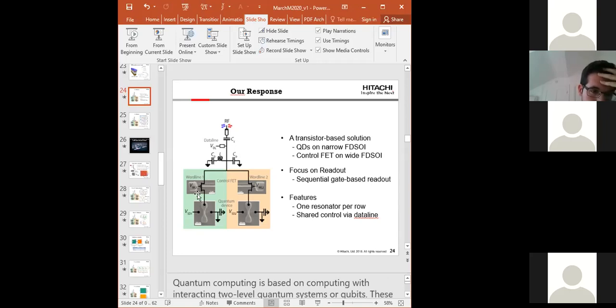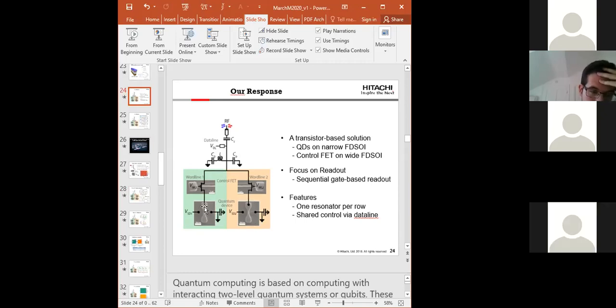And then you disconnect from the data line, and then you go to the next one, and you provide a slightly different data line voltage if you need onto the second device. The caveat there is that the voltage here, while you are not connected to the data line, will vary over time. So you need to manage that voltage variation over time and assess whether you can cope with it.